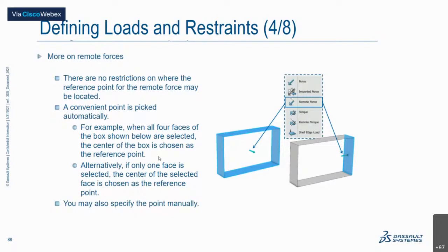You can use this particular command if you require it in such a way, because if you want to define a center load, you'll have to create a point there first, link it to each of them, and then apply it. So in that case, your remote force could be helpful for you. So that is one way you can use remote forces.